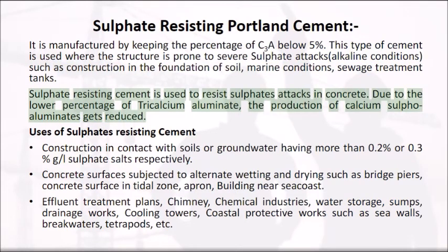Sulfate-resisting cement is used to resist sulfate attacks in concrete. Due to the lower percentage of tricalcium aluminate, the production of calcium sulfoaluminates gets reduced.